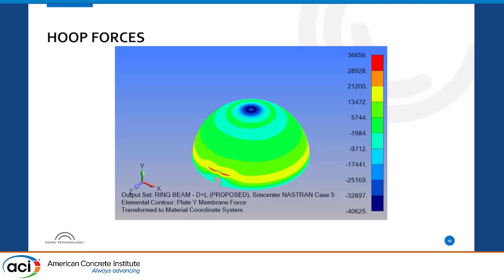On the flip side, if we look out here at some distance away from that opening, we get a constant band all the way around. And so we can see, oh, we're getting some issues with that. We should probably look at that. And our highest stresses in here are not right there. They're above this opening. Okay, maybe we want to look just at a certain section of elements right there.